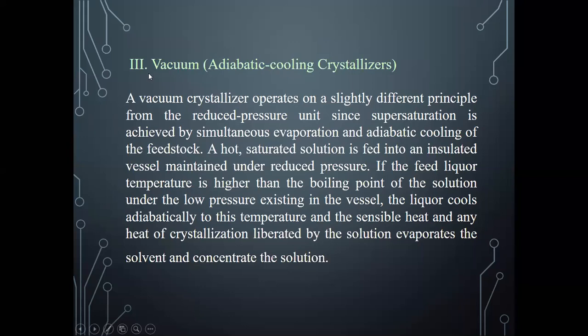So in the third type here, we have adiabatic, so there's no amount of heat that is liberated from the system. The crystallization process is operated under vacuum, so you are able to reduce the amount of solvent present in the feed, and at the same time cool it simultaneously with the lowering of the solvent content.